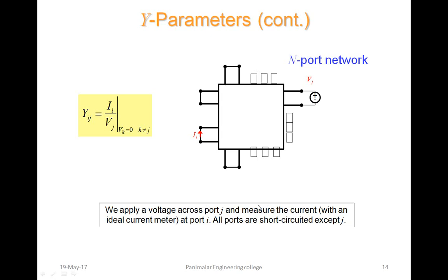In a nutshell, we have to remember like this: for impedance parameter analysis, we have to open circuit the respective port. And for admittance parameter analysis, we have to short circuit the respective port.